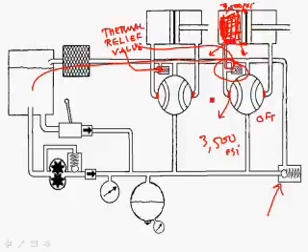Now, although this valve here is operated off of pressure, it's called a thermal relief valve because it saves the system because of the temperature of the hydraulic fluid getting hot and that causing the high pressure.